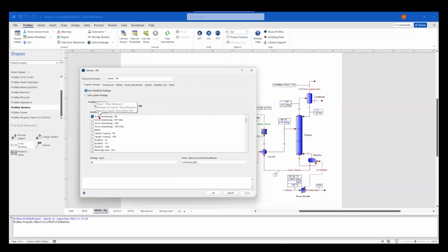Since we have chemical reactions, and those reactions are taking place in the water, and ionic species are reacting, we need a thermodynamic package which will describe this equilibria between ions inside the water phase. That's why we are using the electrolytic package for that.